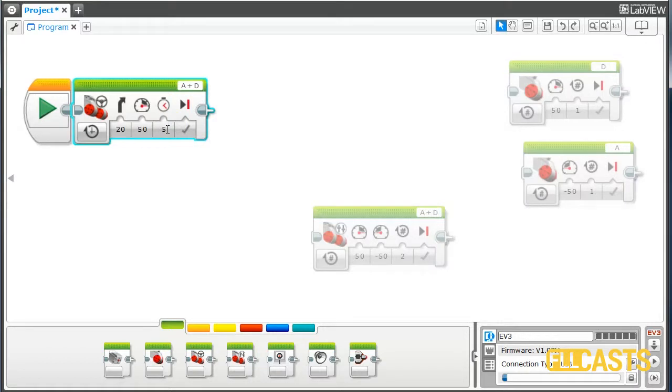Now 5 seconds are not always equal to 5 rotations. It might be true sometimes that rotations are equal to seconds, but it might not be true. For example, if we move the robot with the power of 100 for both motors, and we move this robot for 5 seconds, both motors will probably do more than 5 rotations, because they're moving for 5 seconds with the maximum power.